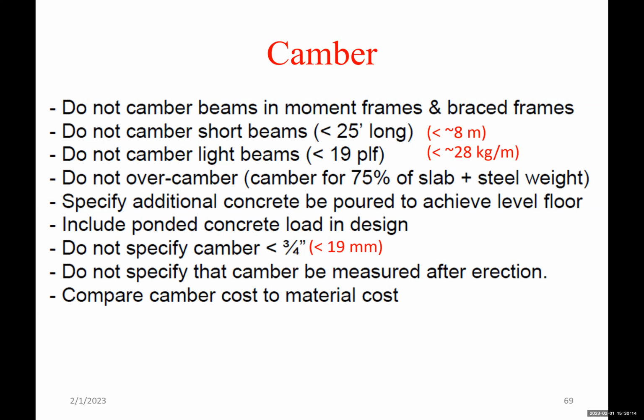Do not over camber. Camber for 75% of the slab plus the steel weight. Do not camber for 100% of the weight, or sometimes 110% of the weight. Camber to 75%, which should be enough to minimize the deflections on your beam.